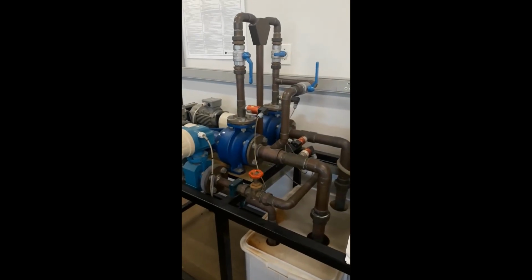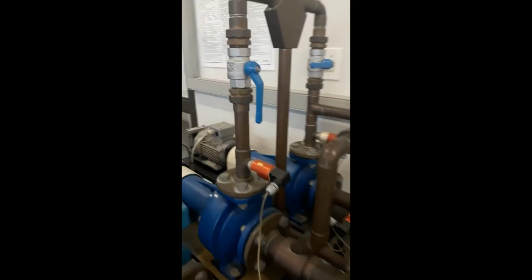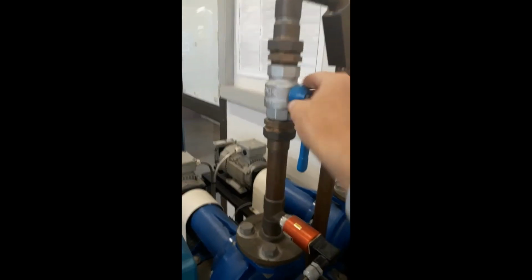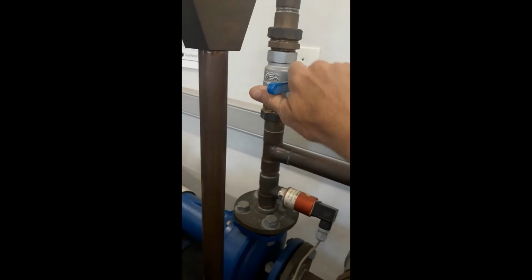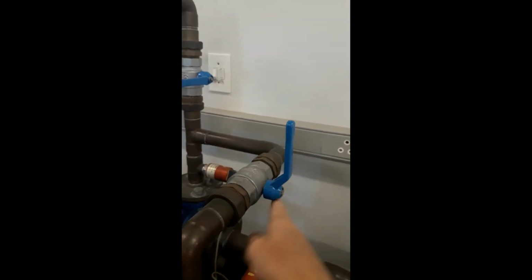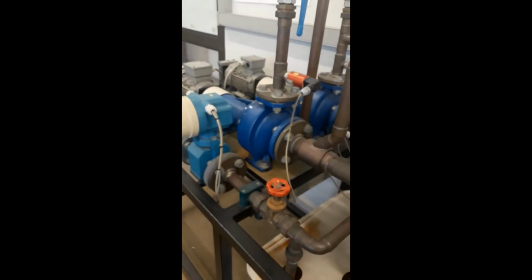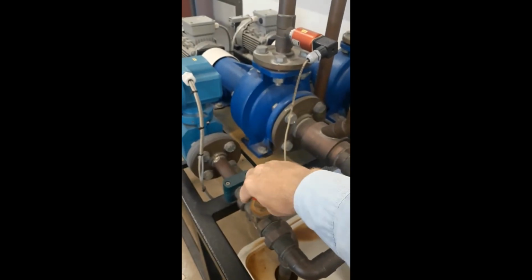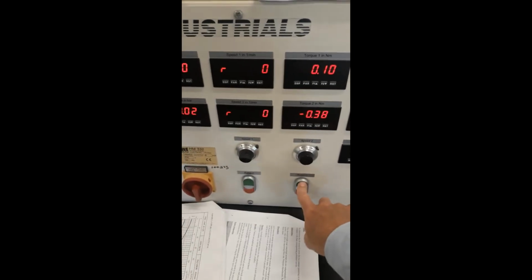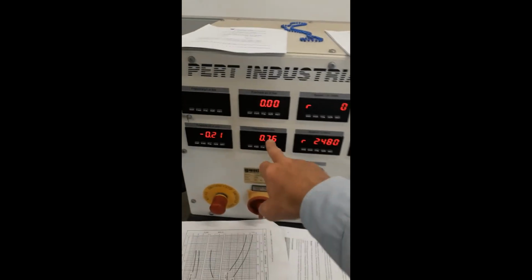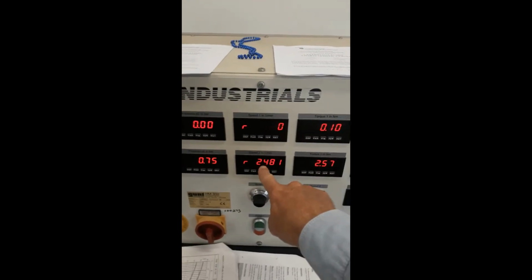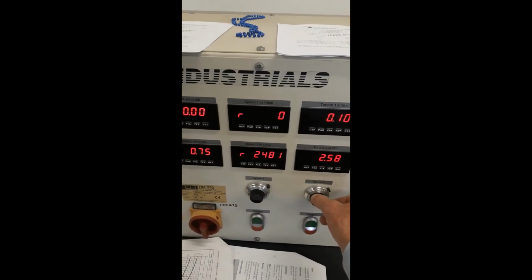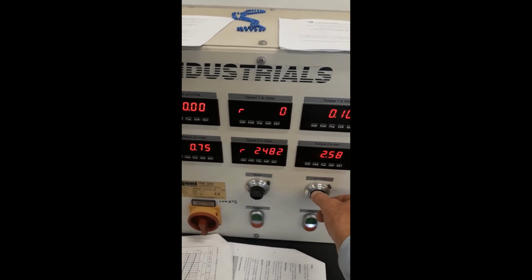For the pump characteristic curves lab, we're going to make use of pump number 2. So we make sure that the outlet valve for pump number 2 is open, and we're going to close pump 1, and we're also going to close the interconnection line. Then we're going to make sure that the control valve is fully open, and once it's fully open, we can start pump number 2. There you can see it's having outlet pressure, and then we just need to adjust the speed with the speed drive, so that's at 2500.